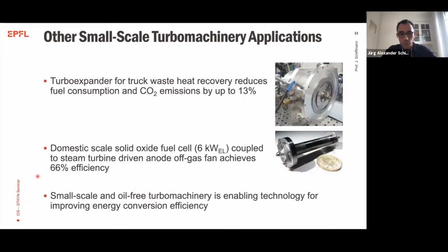Another project which I'm quite proud of is this project here, where we have designed a very small scale anode off-gas fan for recirculating anode off-gas from a solid oxide fuel cell. This machine is not driven by an electrical motor, but rather by a steam turbine, where the steam is actually produced by the waste heat of the solid oxide fuel cell.